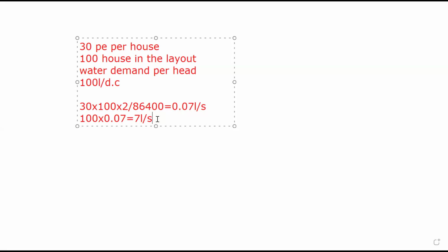You asked us to use the slope of 0.1. So at node 13, which is the initial node, I referenced your point that the velocity should also be considered, and it should not be less than 0.3. It should be between 0.3 and 1.2. So I needed to increase my slope at that level. Then I increased it to 0.18. Is that okay, to have a minimum velocity of 0.3? Yeah, that's okay.